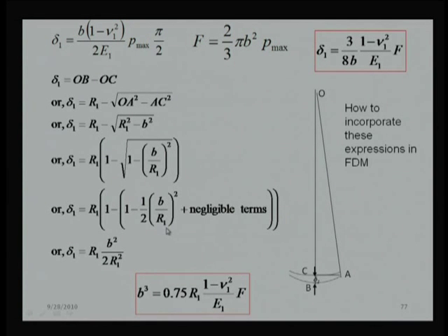Now, the question comes: how do we incorporate this in hydrodynamic lubrication? We have talked about only the solid mechanics in this case. We talked about the deformation in terms of the force, but how do we combine it with hydrodynamic lubrication, which we have discussed in previous lectures, and in which we have more interest? Only when we can combine hydrodynamic lubrication with elastic deformation can the name elasto-hydrodynamic lubrication be given, which, as I say, is one of the optimum tribopair mechanisms.